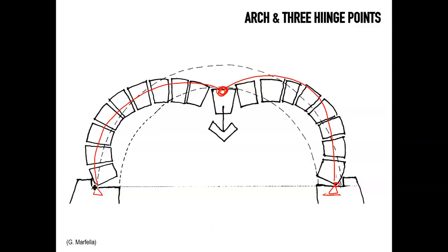This is something we discussed also, if you recall, when we introduced the problem of the lintel, where we said that stone lintels have a tendency to crack at the bottom, and in effect they too tend a bit to work like a structure that is hinged at the 2 extremes, and also hinged in the middle. But these 3 hinges all together still maintain this structure in equilibrium.